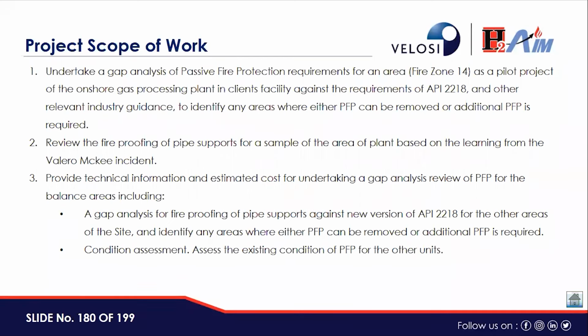Then the scope of work involves the review of the fireproofing of pipe supports for a sample area of the plant based on the learning from the Velosi incident. Then provision of technical information and estimation of the cost for undertaking a gap analysis review of PFP for the balance areas was also included.